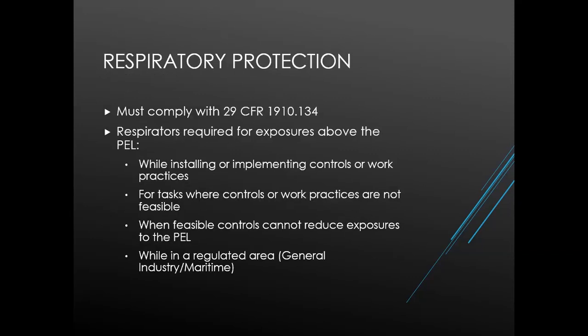If you as the employer will be using respiratory protection in accordance with this standard to protect employees, then you must also comply with the respiratory protection standard 1910.134 and provide those employees with an appropriate respirator. Respirator use will be required when exposures exceed the permissible exposure limit during periods necessary to install or implement feasible engineering and work practice controls.